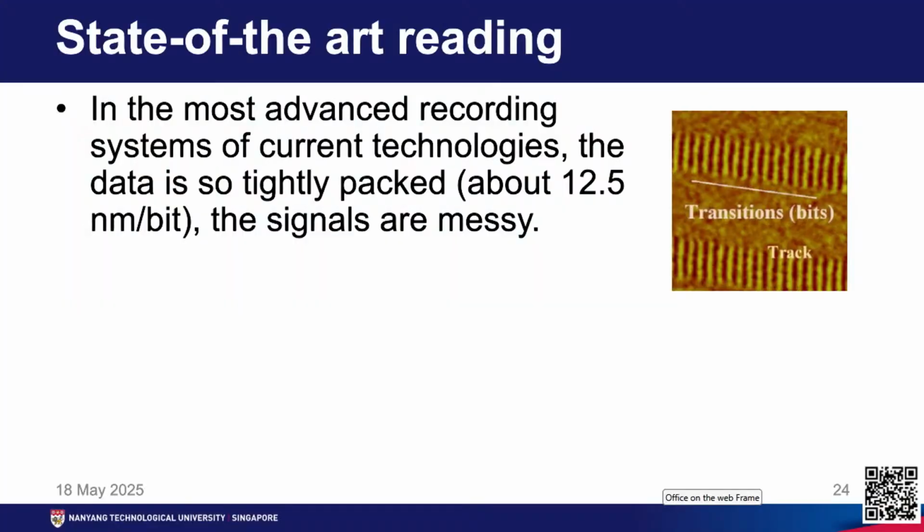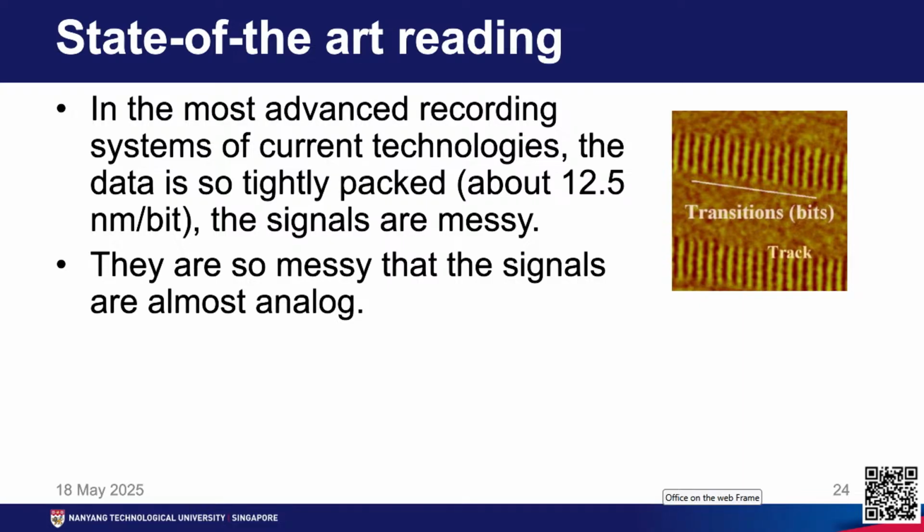However, in state of the art magnetic recording, I asked you a question, how long is one bit, right. Currently our bits are only 12.5 nanometer or smaller. Each line that you see here is so close. In this case I collected this picture using magnetic force microscopy, but in state of the art recording technology, the bits are so close that I cannot take an MFM picture.